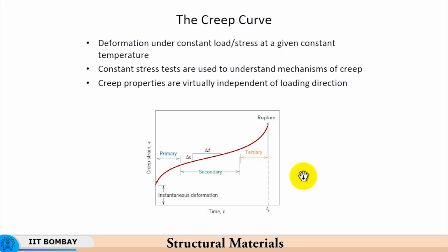So, we have a typical creep curve, unlike a tensile curve. Supposing you were to apply a constant load, or therefore an initial constant stress, then you have some instantaneous deformation taking place here. You plot the creep strain on the y axis and time here. Unlike a tension test where we plot load versus elongation or stress versus strain, here we are talking about creep strain versus time. The reason is that it is a time, temperature, activation energy dependent phenomenon, which means that time is an extremely important parameter.